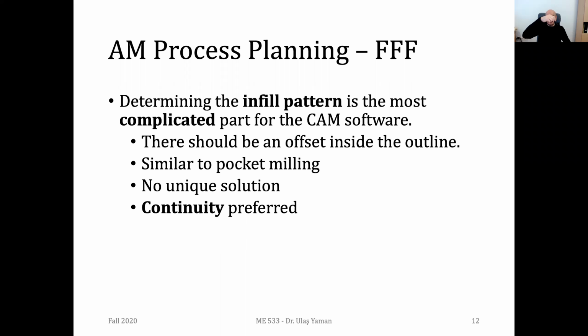You can simply start it once, and once the layer is finished, you can stop the extrusion and go with the next layer. But if you have discontinuous paths, you need to stop your extrusion many times and start many times once again, and that will increase your manufacturing time and also decrease the quality of your prints.